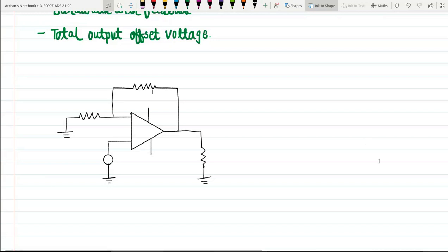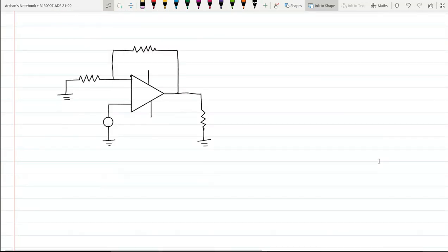Okay, so first of all we will require some circuitry for non-inverting amplifier, right? Now as we have discussed, whenever we talk about the non-inverting amplifier, that means we are providing the supply or voltage signal to non-inverting terminal over here. Okay, so we have applied some voltage, say V in, to the non-inverting terminal of the amplifier. Okay, let us say this is my terminal B and here is my terminal A. Okay, and inverting terminal of the amplifier is grounded.